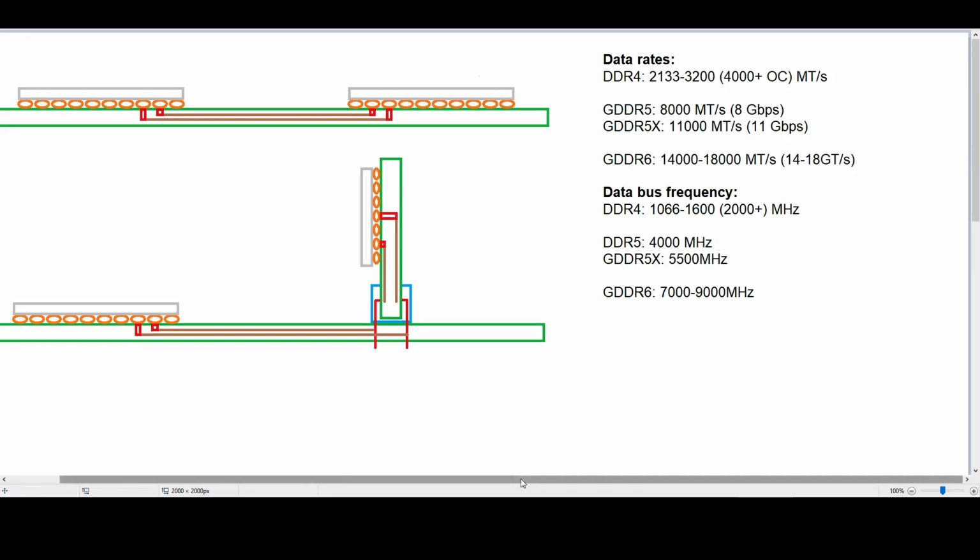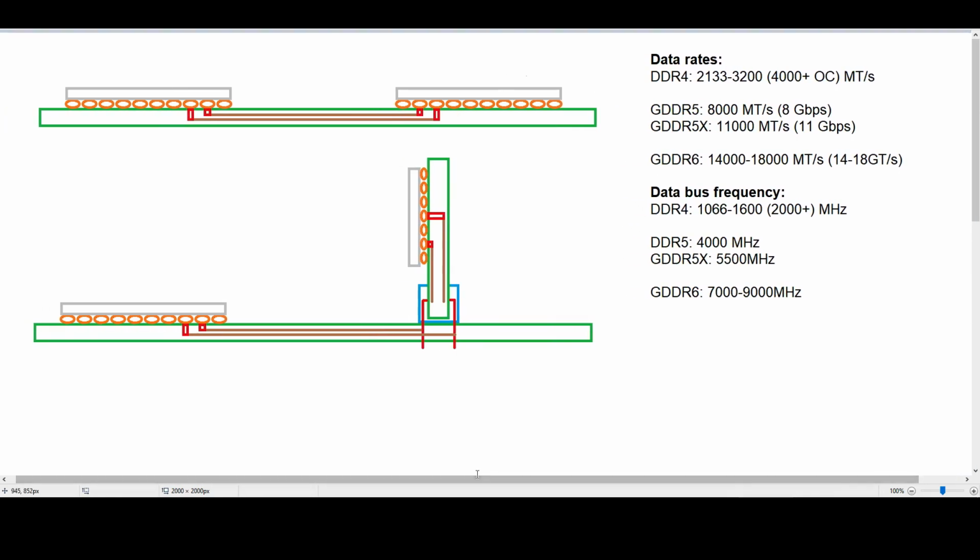And so we'll look a little bit about the signal integrity and sort of how and why it's so challenging, and basically look at what are the difficulties when it comes to organizing a memory system like this. And the short answer to the question is really that having the memory on a card or anything that you can quickly remove, or the user can quickly remove without soldering it, is really difficult to manage in terms of the signal integrity.